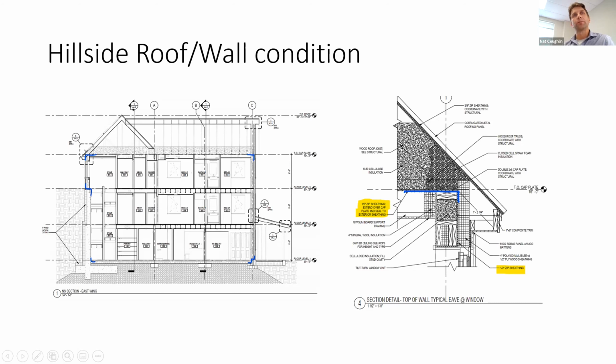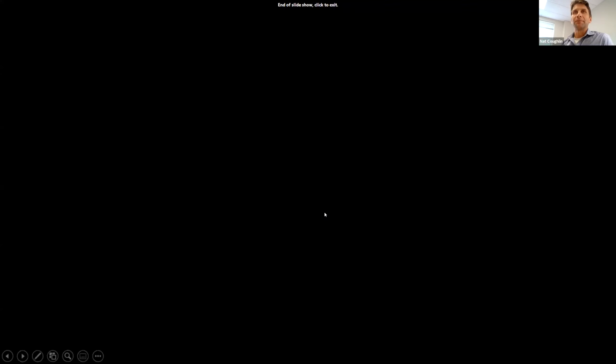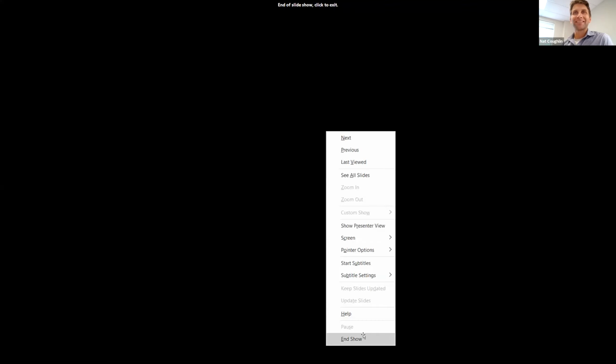This was another where we went under the trusses for the air barrier. And here it was because with a pitched roof, it's really hard to go up and go over the roof because you need a lot of thermal insulation outside of that air barrier or you get condensation issues. So originally they had drawn it right under the metal roof and realized that wasn't going to work. And so they actually dropped it down under the trusses. So that was sort of a quick touch.